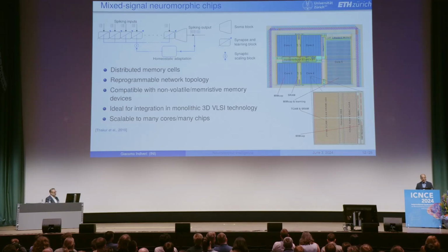The hope is that if we can co-integrate CMOS with memristive devices, we can greatly reduce the size and in the same area greatly increase the number of neurons. So we could take advantage of the density. The advantage is not going to be that big because each synapse in any case will have other transistors. So it's not going to be a very, very dense 1T, 1R crossbar.